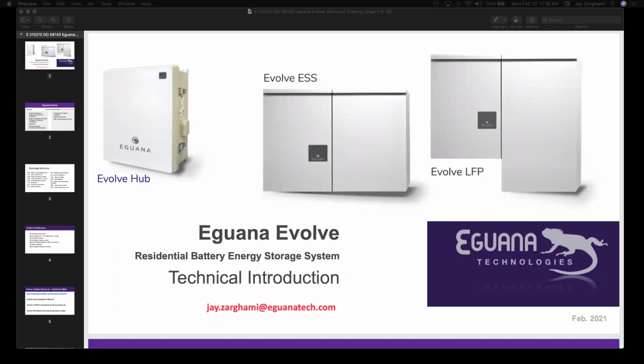So if you've got a 10 kW battery system with variable capacity, up to 42 kilowatt hours, that paired PV system would probably also follow the same one-to-one guideline with a slight oversizing on the nameplate rating. So you're looking at probably 10 to maybe as much as 12 kW of PV on that backup loads panel.